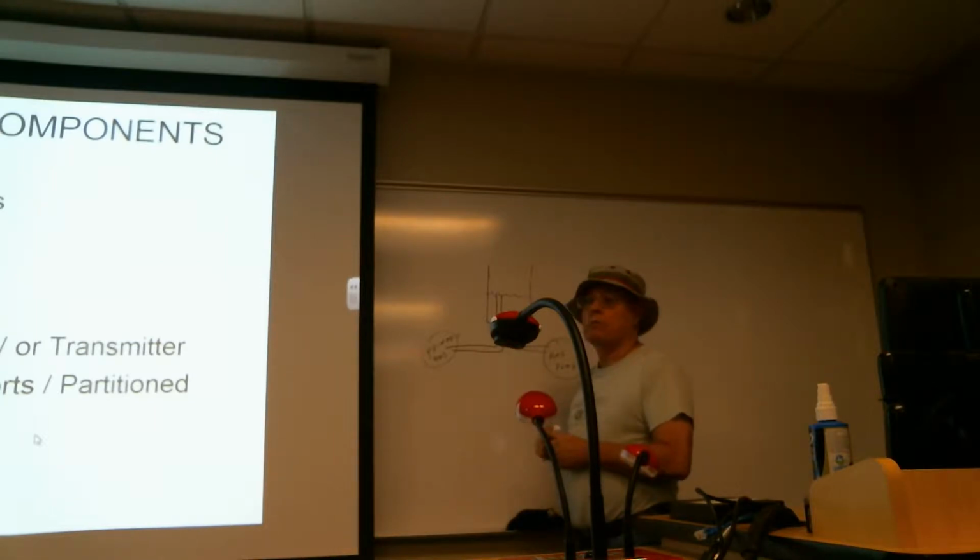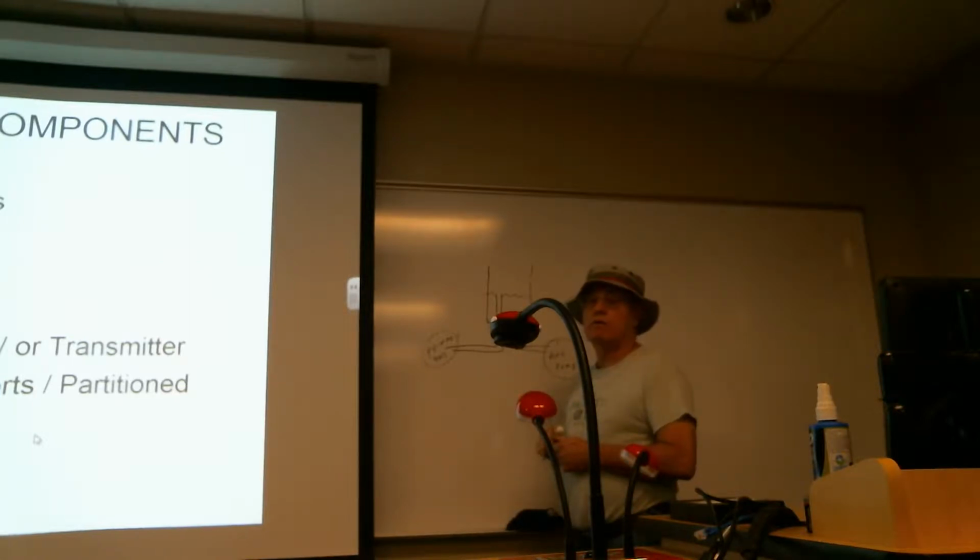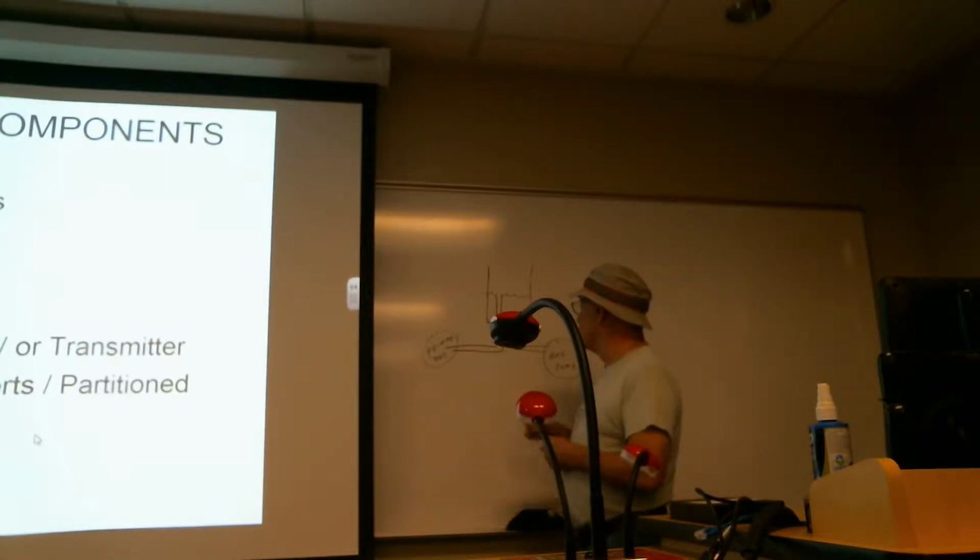Understand too, the real purpose for a standpipe is another function as well. The primary function of a standpipe is to prevent contamination from entering into the primary pump. The particles will normally settle down to the bottom of the reservoir, maybe in sediment space, but again, an additional function of that standpipe is to prevent contamination from getting into the primary pump. But we can use it for segregation of fluid.